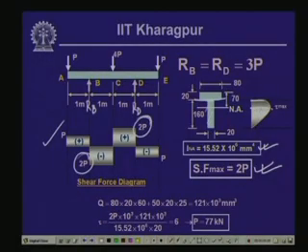So, we have some value of the shearing stress at the interface between the web and the flange, and that we are calling the minimum shearing stress, tau minimum. So, if we compute the value of the maximum shearing stress at the neutral axis, then again from tau equals V Q by I T, V is known now which is 2 P, Q is equal to A y bar, which is above this neutral axis, and this is what is Q.